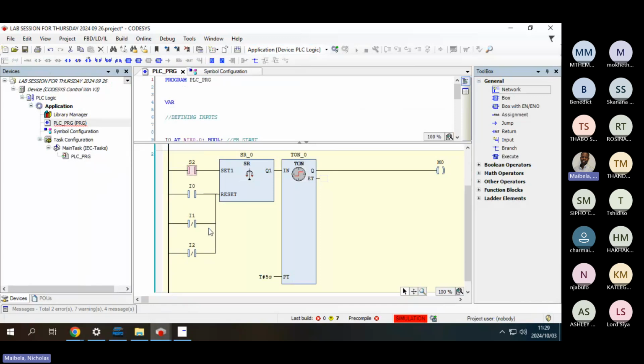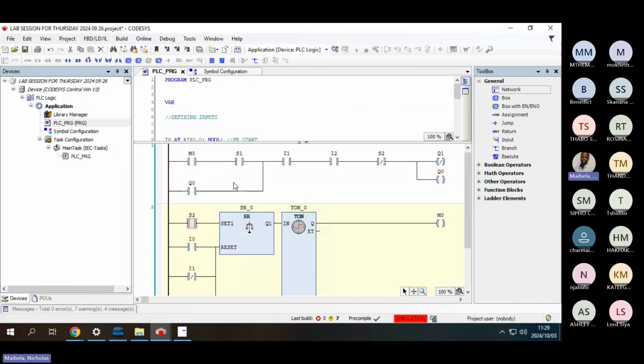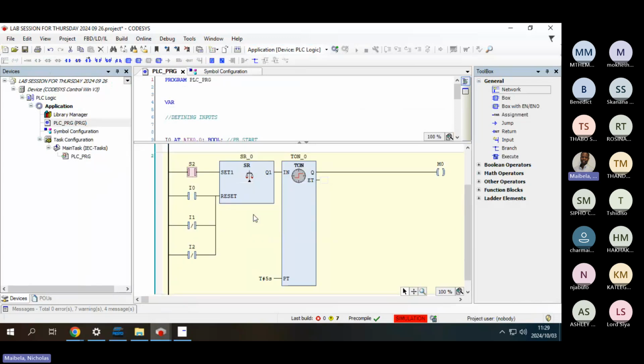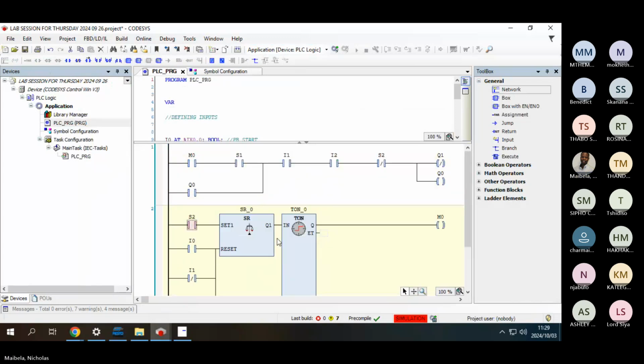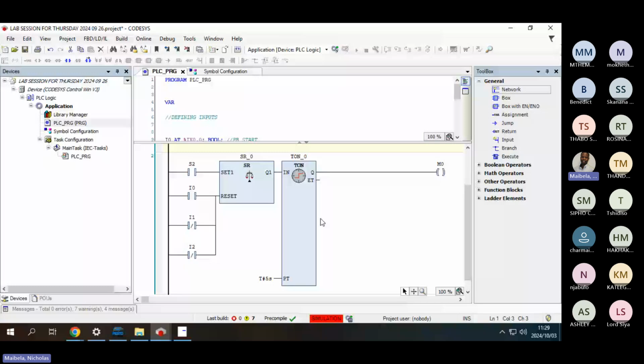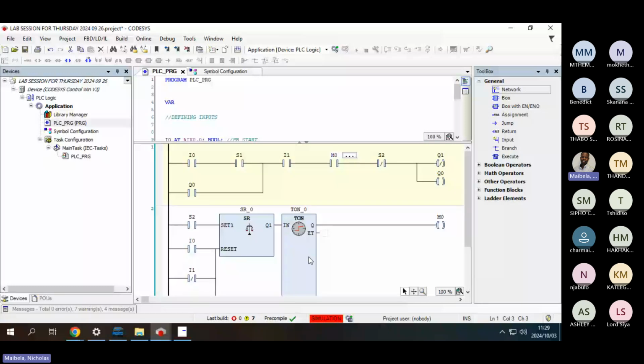Okay. So we'll now swap our memories. So I0 comes back here, right? And then we're saying I2 is the contact responsible for delaying retraction, right? So we swap that with I2, right?